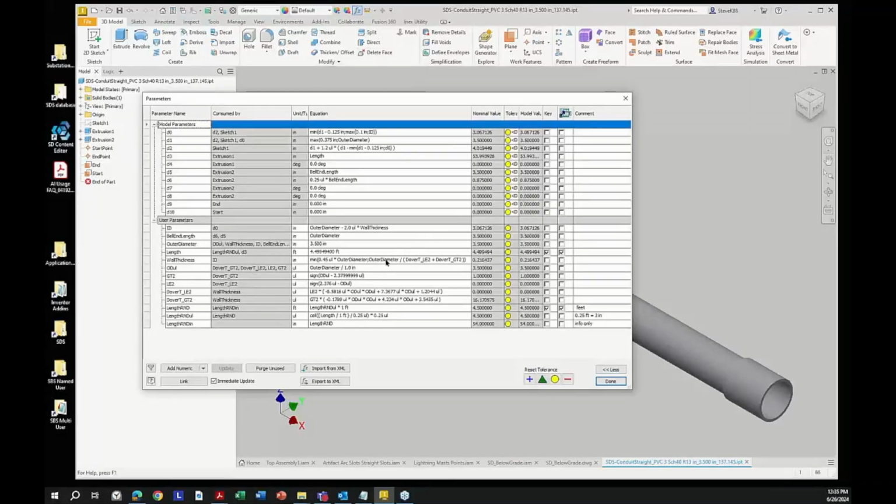And what I did in here, I modified the part. So inside of the part, I've taken the length. This is the length we cannot change. I can't change this, right? We do not want to change it. And what I did, I made a new parameter called length round, and I made that rounded up to the nearest 1/4 foot, which is 3 inches. So I put a ceiling unit length on there and brought it up, and that is my round length. So I put that right into my model.